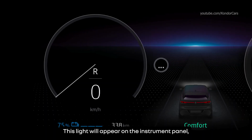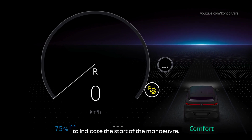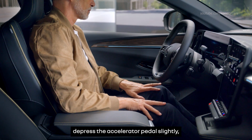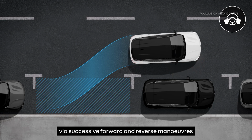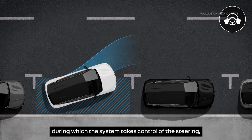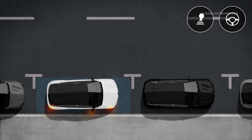This light will appear on the instrument panel, accompanied by an audible signal to indicate the start of the maneuver. You should now let go of the steering wheel, depress the accelerator pedal slightly, and follow the instructions on the screen. Your vehicle is then parked via successive forward and reverse maneuvers, during which the system takes control of the steering, gear selection, and braking.